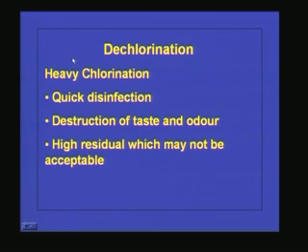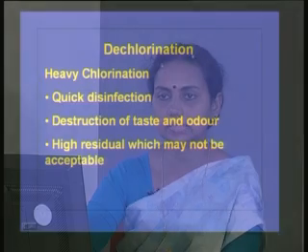In postchlorination, if you want to find out the dose, what we have to do is find out the break point and add a dose which is slightly higher than the break point, so that the required residual chlorine is present. Now, we will see what dechlorination is.